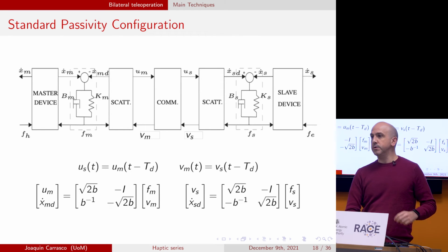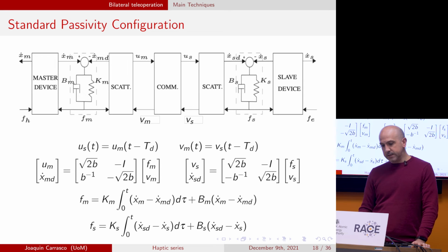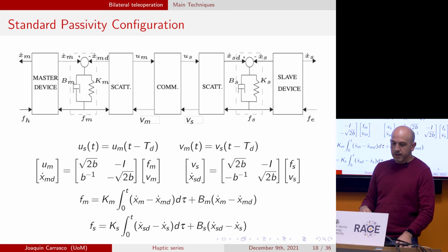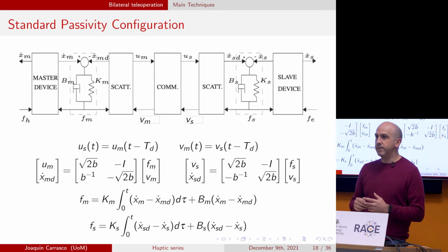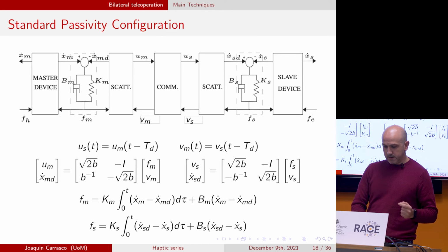And then we are going to introduce a spring damper system between both of them. And these two equations give me the spring damper system between the velocity that I want the robot to have and the current velocity of the robot.